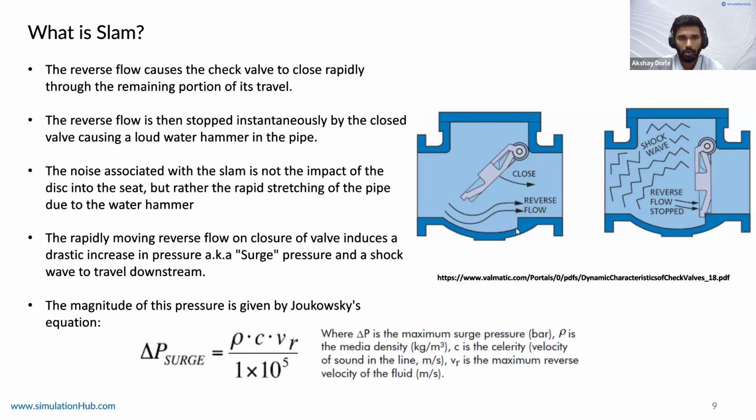It's actually the sound of the pipes stretching inside this abrupt pressure rise inside the pipeline. And it almost sounds like a metallic noise. So even resilient seated valves and metallic seated valves will have almost the same sound in water hammer.